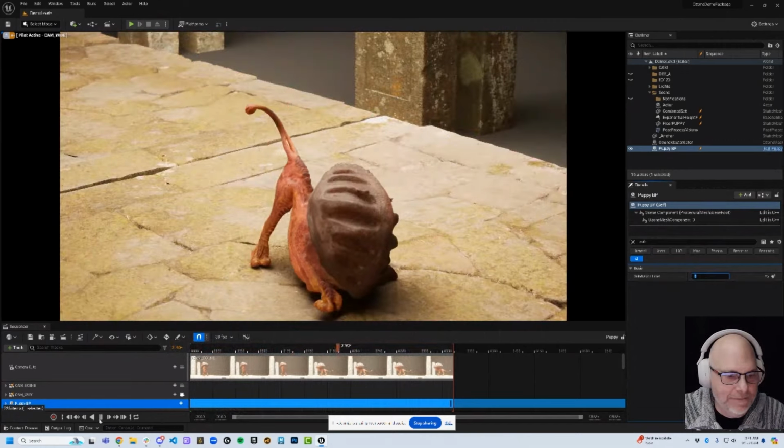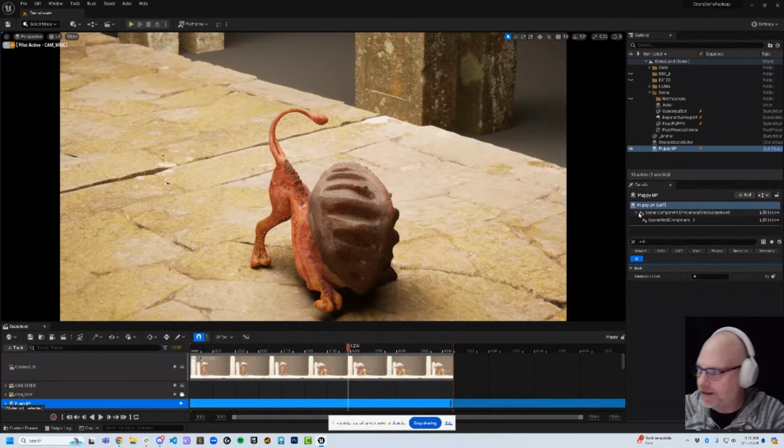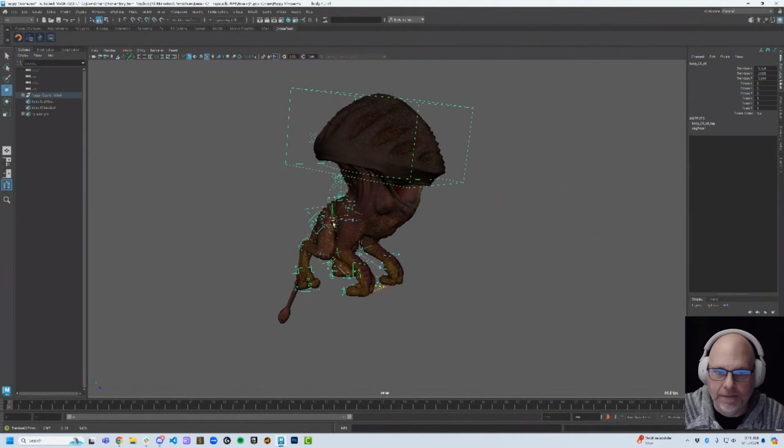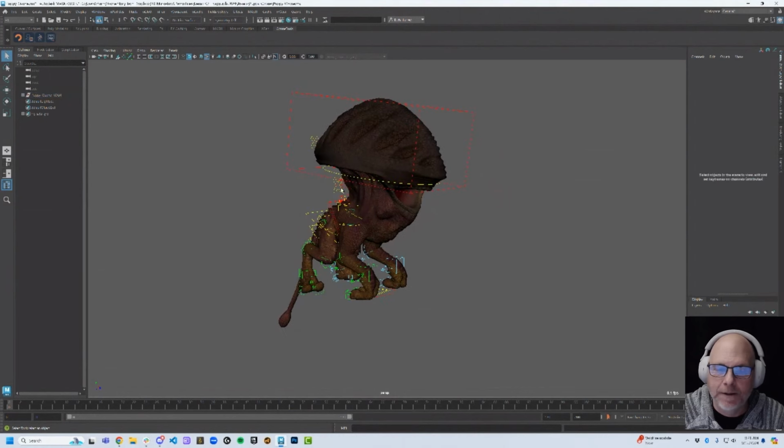100%. And then if we look at this now inside of Maya, we'll jump over to here. Here is that same asset in Maya, right? I'm moving this character around, and I'm using an off-the-shelf puppet system. I'm using M-Gear, right? Oh, cool. So the joints, the IK, the space switching, the puppet, if you will, is all M-Gear. It's a standard Maya tool. And what we've done is we've taken the Maya skin weights out and plugged in the Ozone deformers. So basically, we're treating the puppet as like a scaffold, right? And we're hanging our deformers on top.